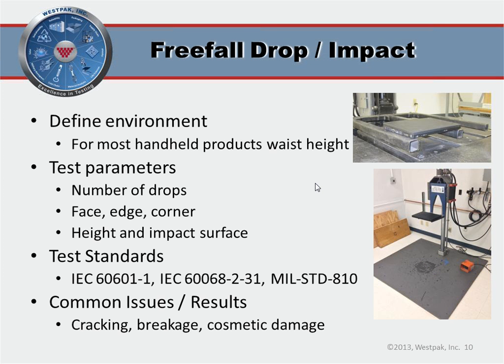And the impact surface. Common impact surfaces we use are carpet, laminate flooring, wood, ceramic tile, concrete, or steel. The lower drop test picture here is a steel plate. Generally, harder impact surfaces are more severe. Also think about testing to level, as I mentioned, the 1 meter drop, or testing to failure. So if you get a more severe drop from, say, 2 meters and a product breaks, how does it break? Is the breaking just cosmetic, or does it pose a safety issue, etc.?